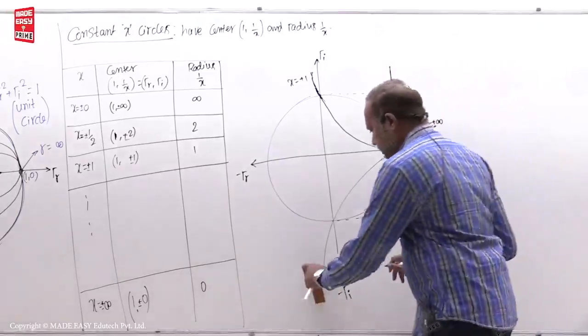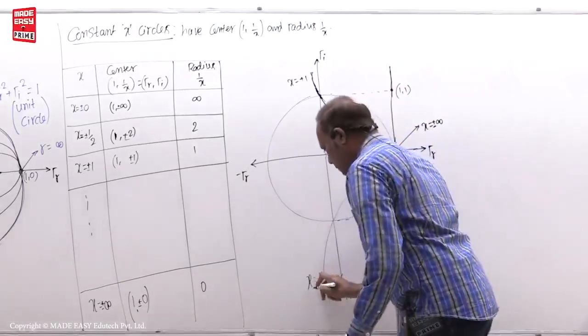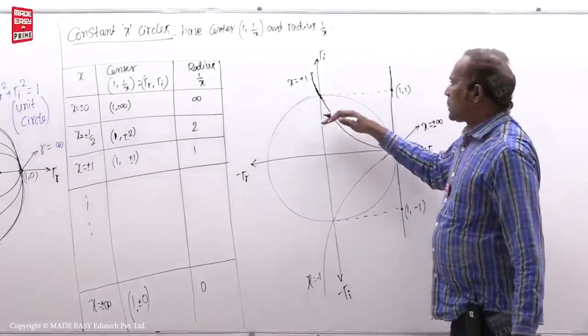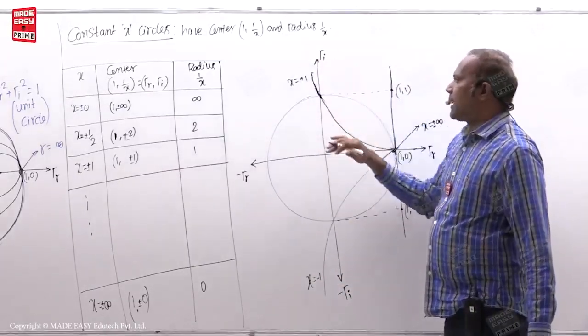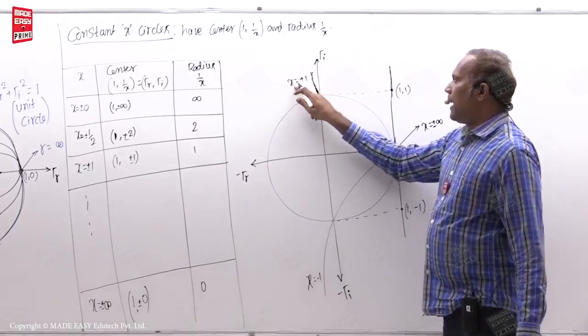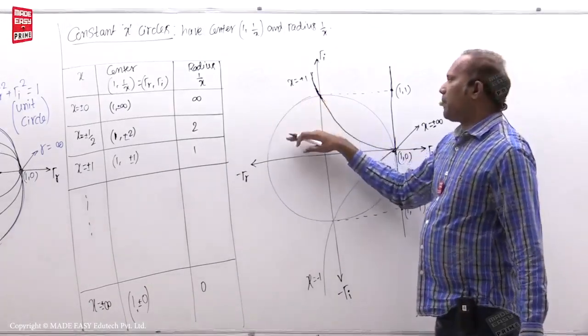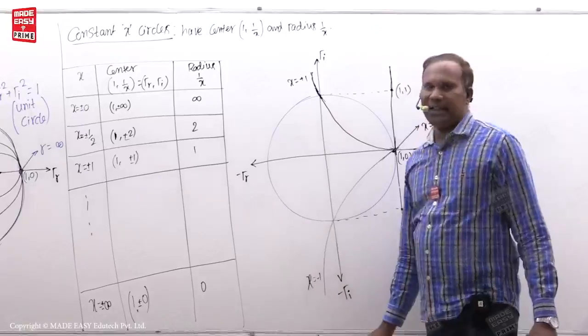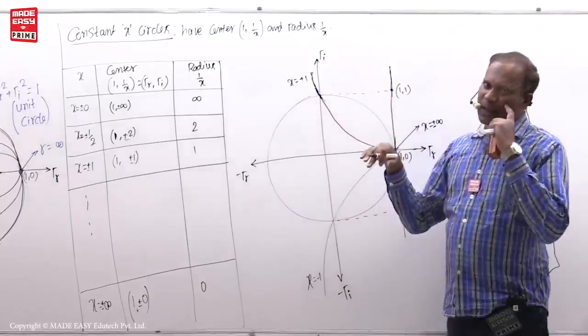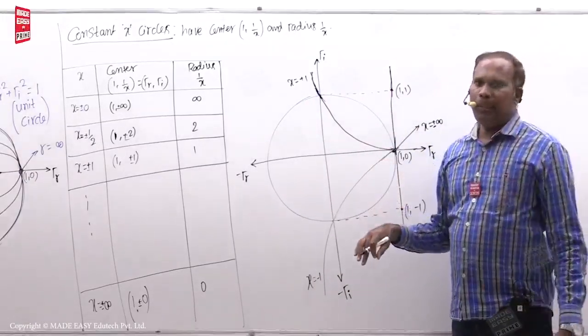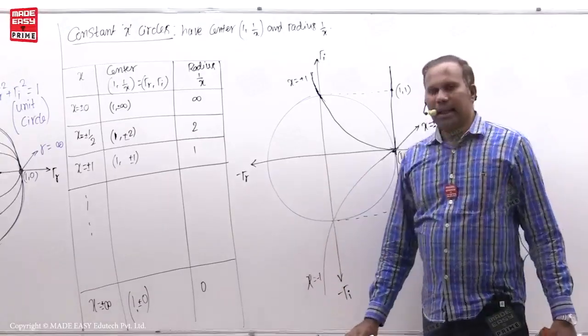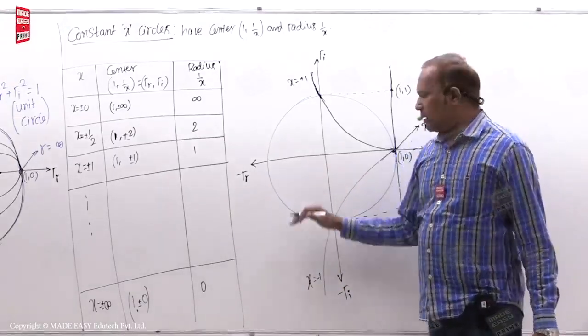That is why on the top side there are plus jx circles, because you will have r plus jx. So the top side is plus jx, the bottom side is minus jx. The top side, plus jx, means that is the inductive part of the impedance, and minus jx means the capacitive part of the impedance, on the bottom side.